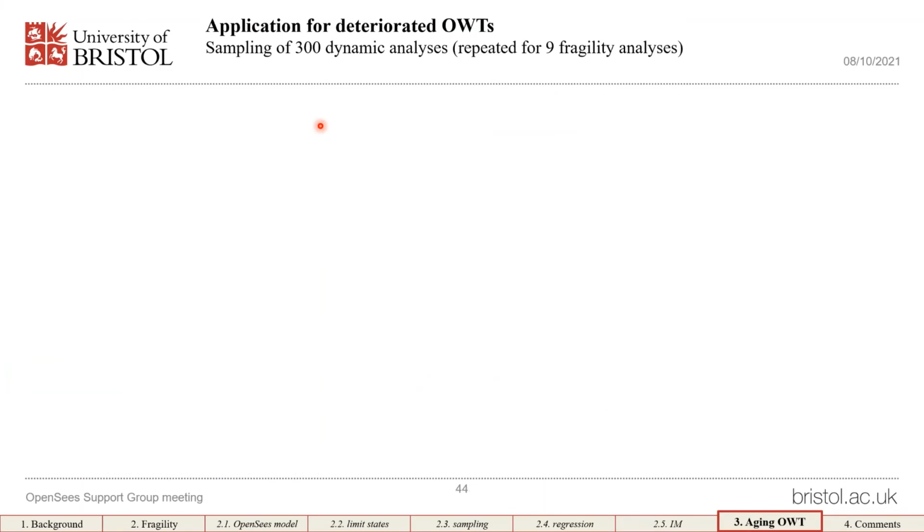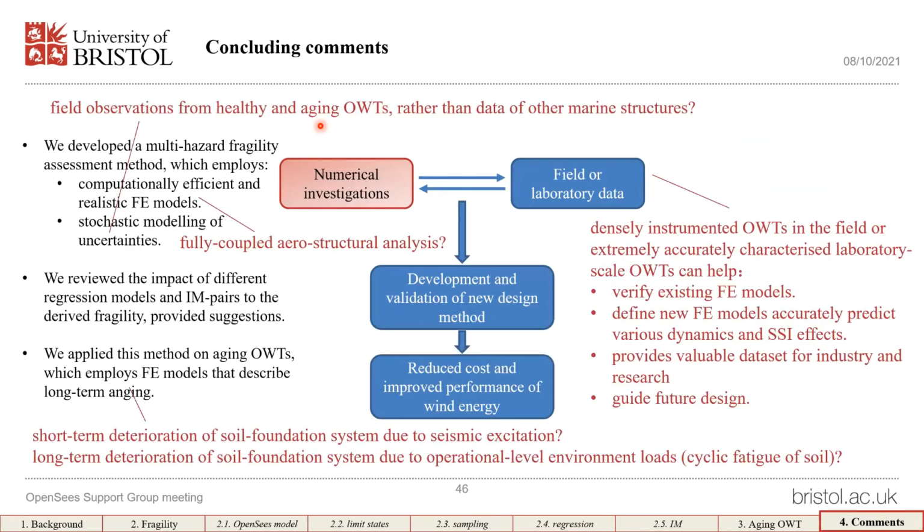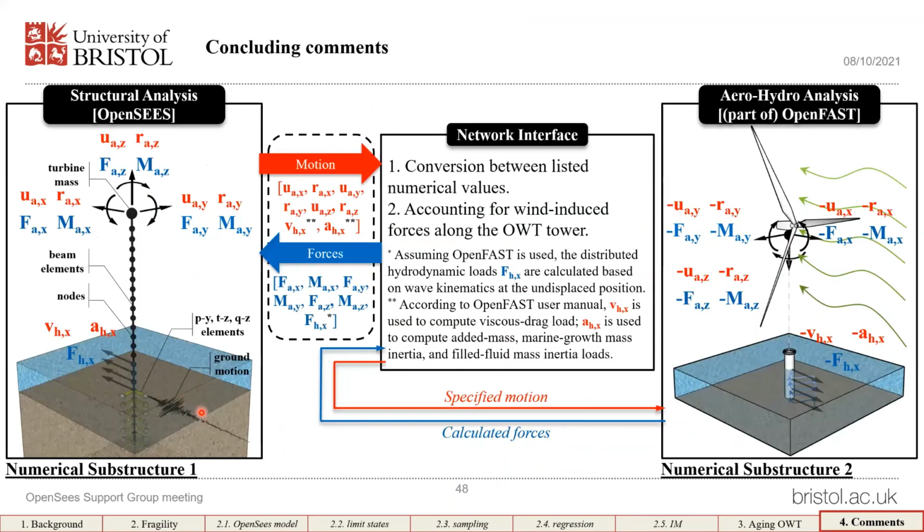I'm just taking this figure here for illustration. The earthquake is just records, but the direction of the strong component, or maybe just the X component of the ground motion, was considered as a random variable, and the direction of the input was adjusted accordingly.